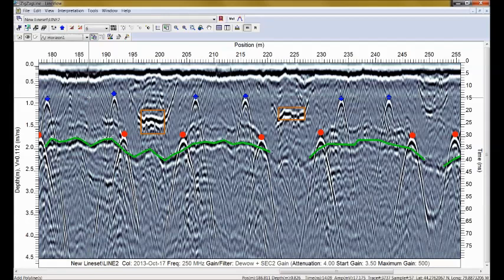So when a polyline is the active interpretation and I use the garbage can and go into delete mode, I want you to notice I can delete points. If I go up to a point, I can put that point in the garbage can. If the cursor is between 2 points, it turns into a pair of scissors, and that allows me to actually cut the polyline. You see, I cut the polyline and I left a gap in it. Now there's a gap. My polyline has become 2 segments in here. And so that's what that's for. I can delete points, or I can delete the line that's in between the points as well when I'm in delete mode with the garbage can. Okay, so I'm going to come out of that mode for a second.